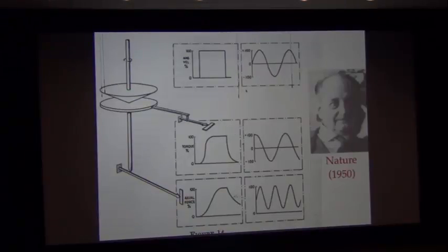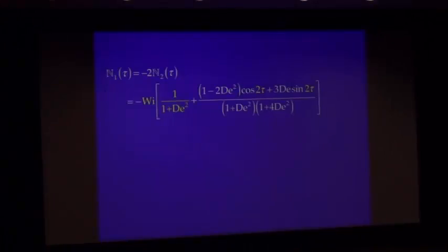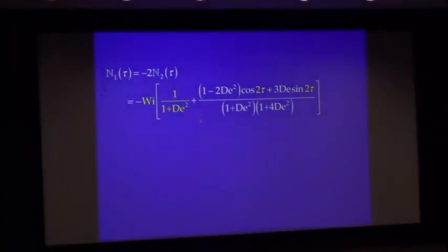He said, well, if I subject it to a sinusoidal deformation, or that corresponds to a cosinusoidal shear rate, then sure enough, I'll expect the shear stress to cause a sinusoidal torque out of phase with the deformation. And then I will also expect a normal stress response about an average value. You see, so there's a zeroth harmonic, and then it will have twice the frequency of the test. And so, indeed, when we do these calculations, we do get results like that.